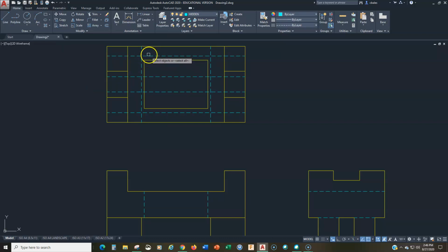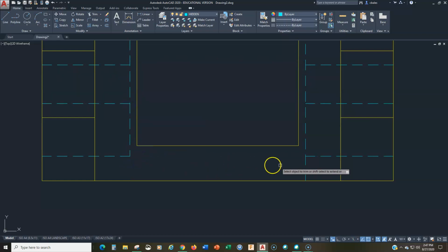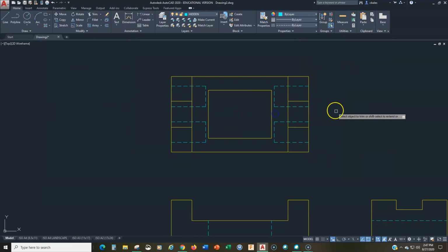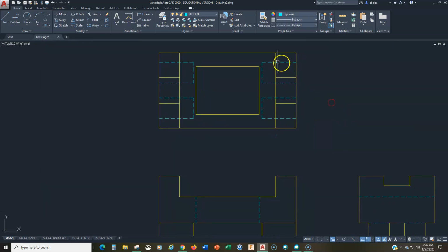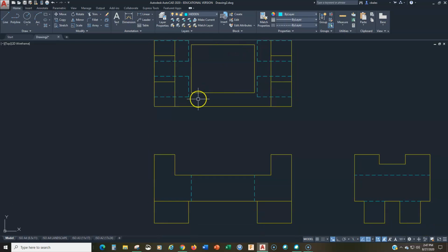And now I can trim, and this is going to be a bit of a challenge to make sure that we trim everything out properly. Right, and that should go, and that should go. Okay, so what you see right here, 1, 2, 3, 4 are the 4 feet as hidden features. Okay. And I do believe that is it for the top view hidden lines.